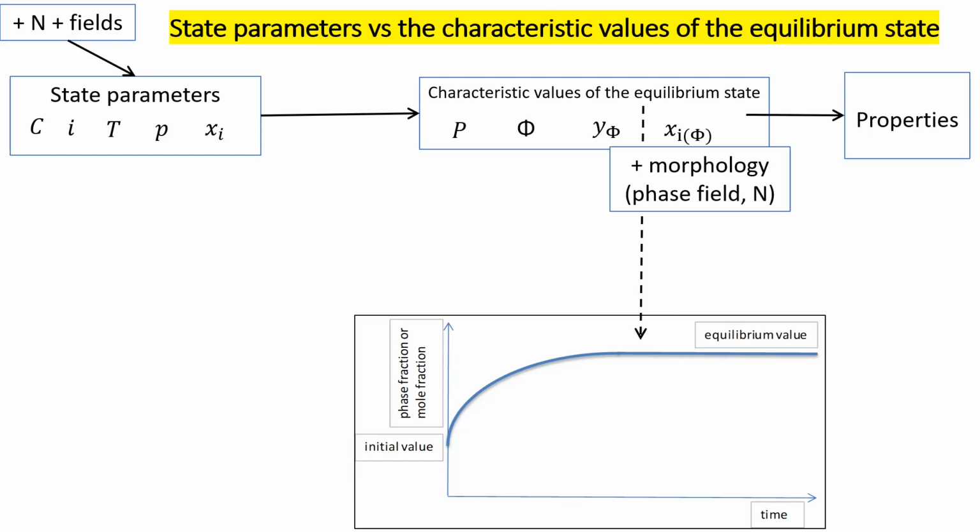Now, it means that we also need the phase field modeling. What is the phase field modeling? This is a complex modeling. The first step is actually what we do here, the Kaptay type calculations, and then all what I mentioned before, diffusion, nucleation, phase transformation, etc., growth of the phases, precipitation, dissolution phase, etc., everything is included in the phase field modeling. Okay? So now we have the properties, which are mostly determined by these equilibrium values.